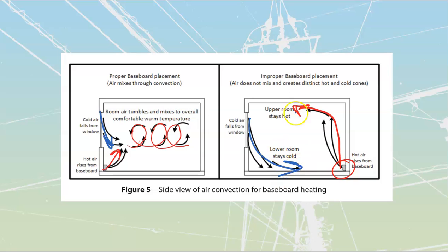And what we're going to do is form this line. It's called the thermocline. I don't know if any of you fish at all, but if you've ever been on a boat with a fish finder, you're going to see one line partway through the water column where the two heats have separated, whatever the water temperatures are. We call that the thermocline. The thermocline exists inside of rooms as well. If we did this, we would end up with uncomfortable heat up top, and a lot of coolness down below.